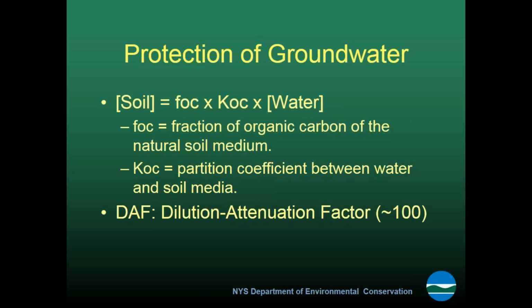If you have them in your drinking water supply, the granular activated carbon filters are generally very effective at taking all of these out. The exception to that rule is 1,4-dioxane, which is so hydrophilic. It loves staying in the water. It's very, very difficult to remove 1,4-dioxane. But almost all of the other organic compounds are removed very nicely with the organic carbon.